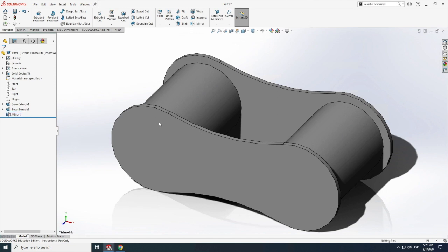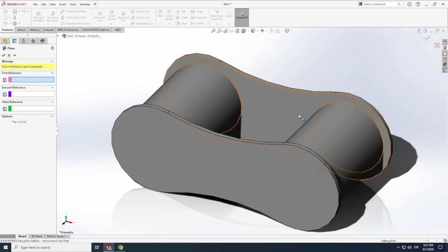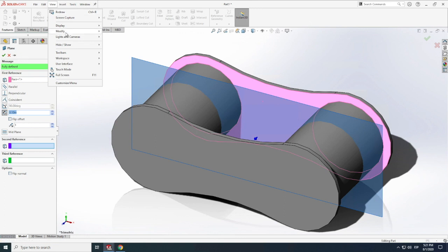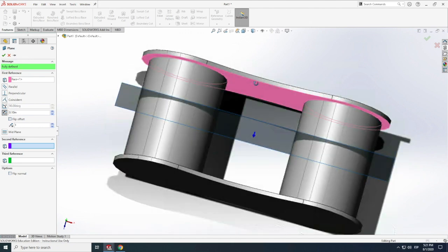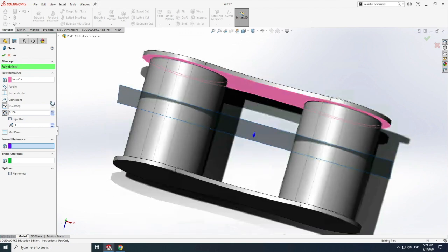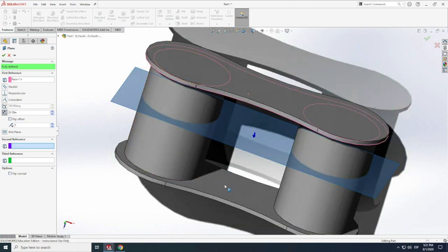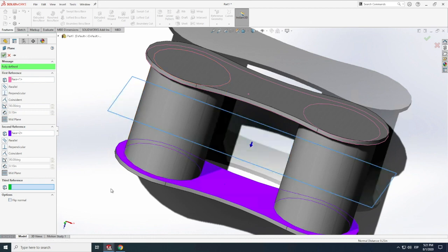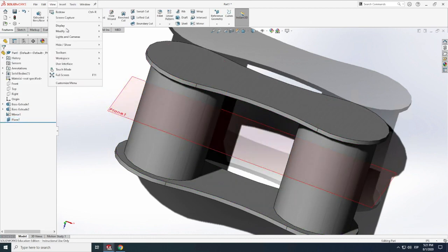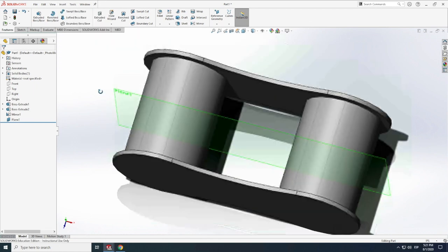There we got it. We're still not quite done, because first thing we'll need afterwards is to insert a plane that is between this and this. So I'll click in here. Now I'm gonna go here to view, modify, rotate. You need always two references, so I'm gonna click escape. Now I'll click here. That plane is gonna be right in the middle, so we'll need it afterwards. And so we'll go here, view, modify. Let me just come back in here.